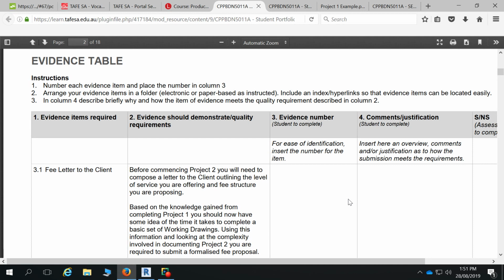We're going to do a few more drawings. We're going to get some more details out of this because it's more complex. Apart from just that one long section, we'll do a cross section as well. So we'll have 2 sections with this drawing, and from that we'll probably end up with about 5 or 6 details to work through as well. That's why it takes a little bit longer to do this one, because of understanding how the materials work in the balcony set down and tiled and all those sorts of things.